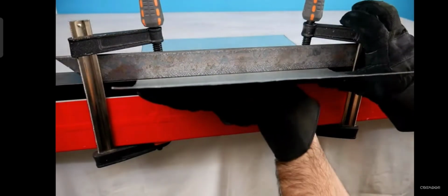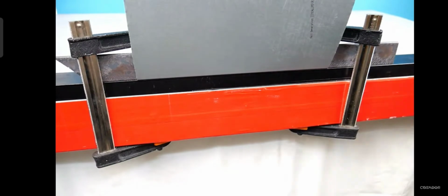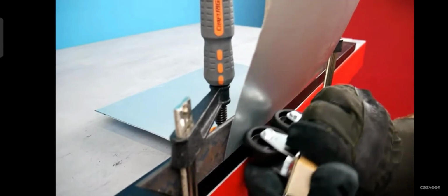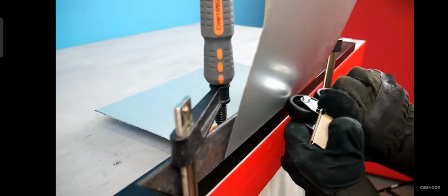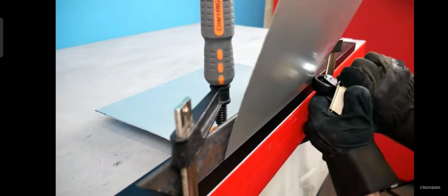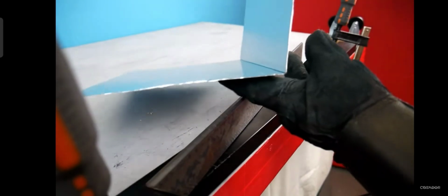With the sheet metal clamped, I help it a little with my hand due to the thickness of the sheet. Then I roll the roller as close to the intended bend as possible. The roller works by pushing on a small area like the hammer. However, it doesn't dent and warp the metal quite as much. I continue to refine until the bend is sufficient. And once again, it's done.